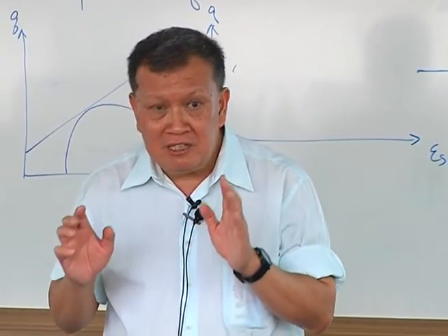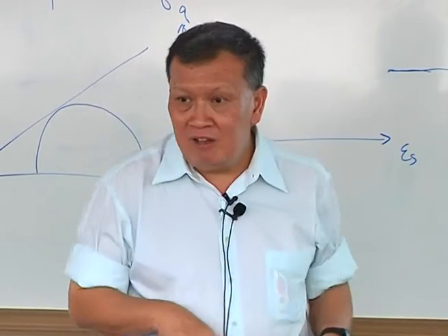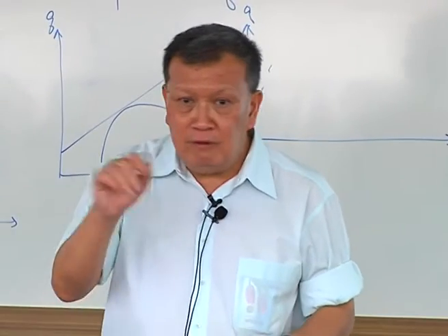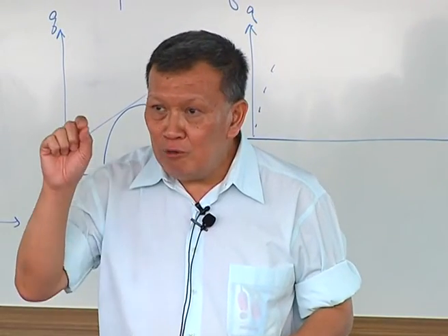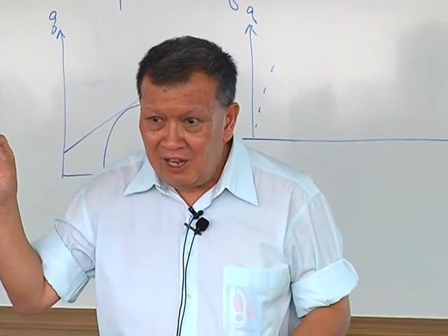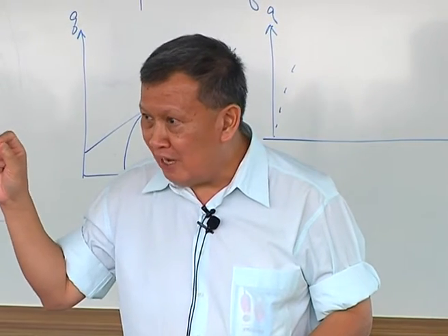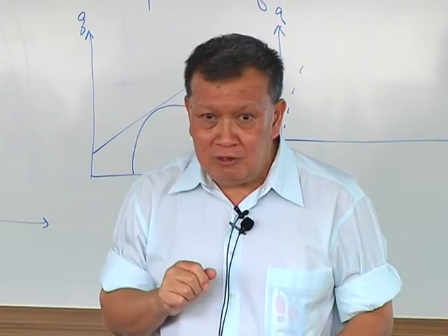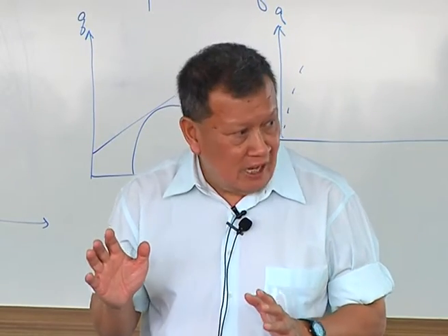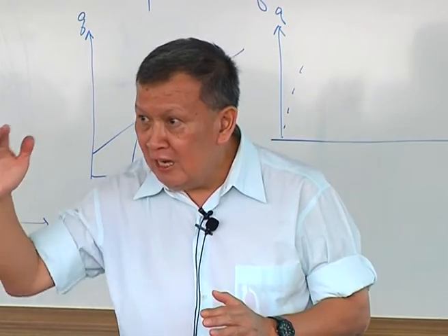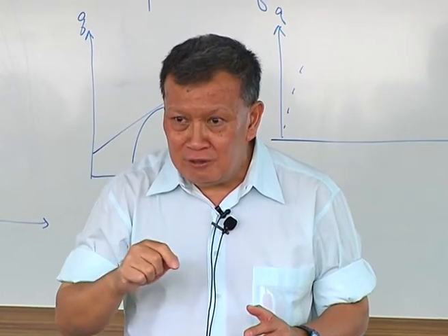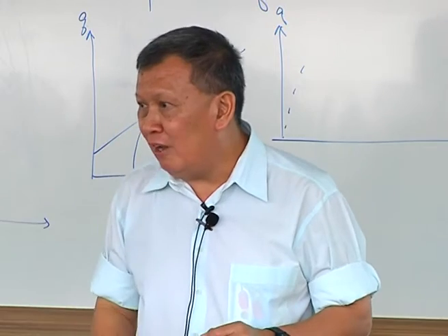Now, Plaxis doesn't calculate the M value directly. What Plaxis does is, you give it 25 degrees, and it will go to Jaky's relationship and say K0 equals 1 minus sine phi. That gives you the K0 value. And then what Plaxis does is fit an ellipse so that when you put it through one-dimensional consolidation, it gives you that K0 value.